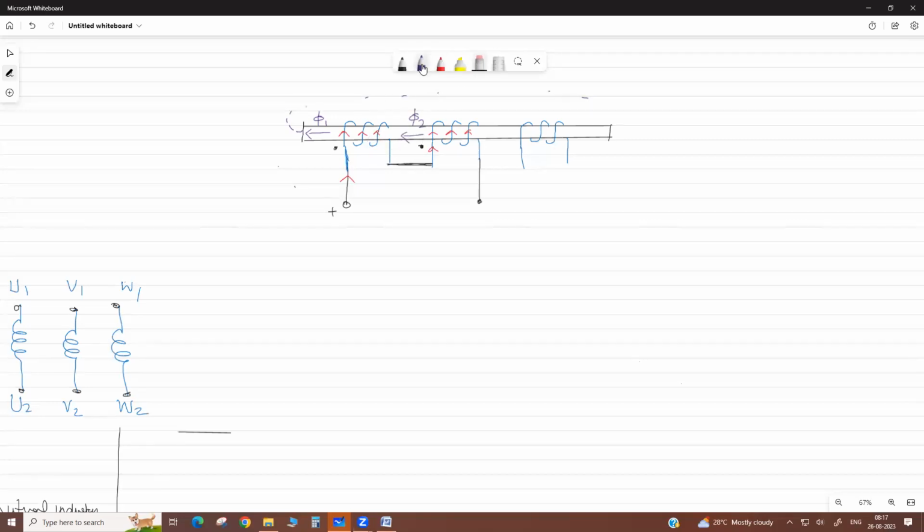That is why in that case, with L1, L2, there is mutual inductance. The flux produced by this coil links with the other, and the flux produced by the other also links, because it comes and returns again. So both coils are additive in nature and support each other's flux. The total flux linkage is high. In that case it comes L1 plus L2 plus 2M, if there is mutual inductance, so it is supporting.